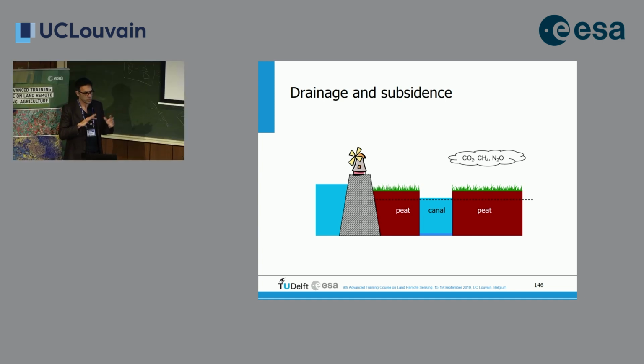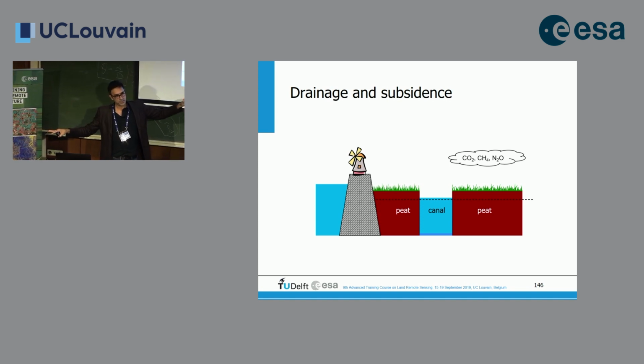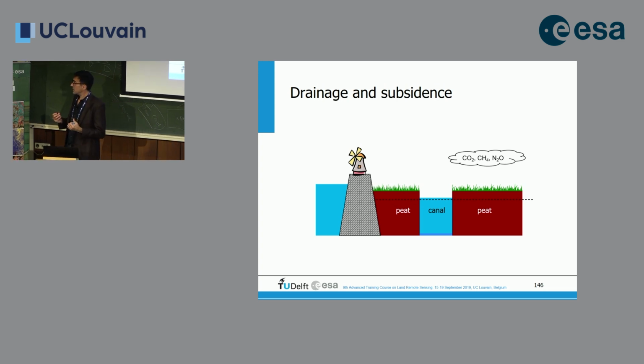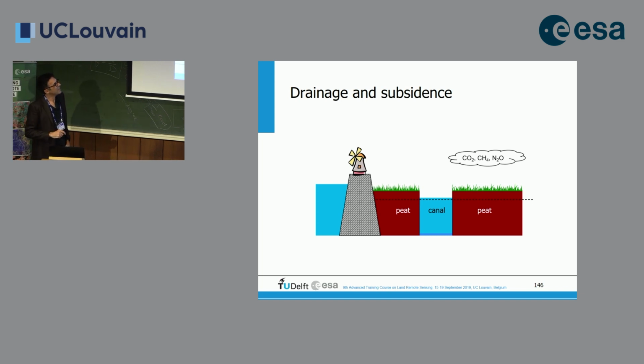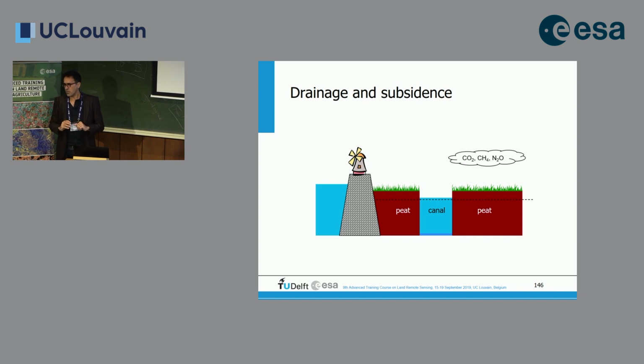Leiden, Haarlem, Utrecht, there are all these cities in the western part of the country, which are centuries old, so they have old buildings. Now, if you lower the water level in the pastures, the water level under the cities also goes down. And that has an effect on the foundation of these buildings, right? Some of these buildings are built on wooden poles. If the water goes down, the poles will start to rot, and there will be a lot of damage to the buildings. So while we have been doing this for about 600 years now, we're reaching a kind of tipping point, because now you see that more and more damage in the old cities will start to occur.